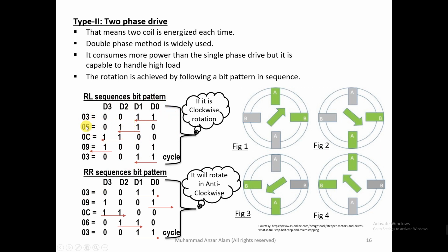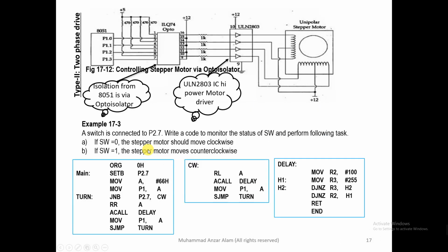Remember this 6 is loaded on the first half byte of port 1, or the accumulator, so instead of 06 we can also load 66. The pattern will always remain the same, but we save the bit value inside the accumulator. So instead of 06 we can load the accumulator with the 66 value, and it will generate again the same pattern.